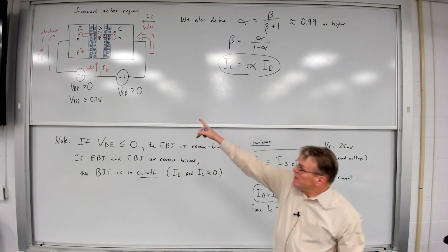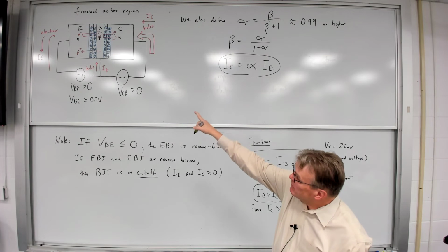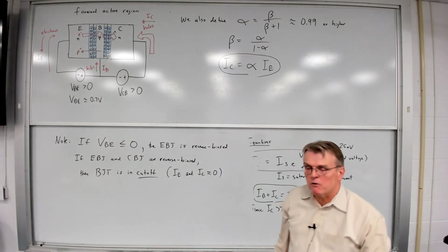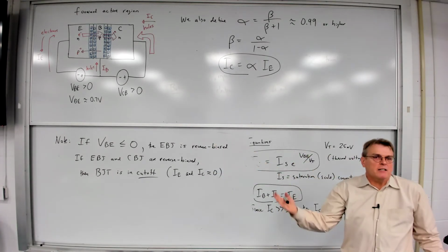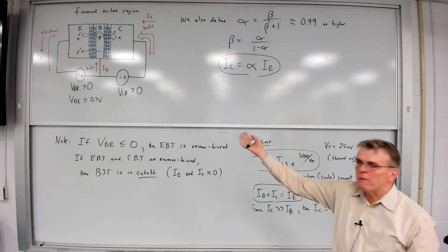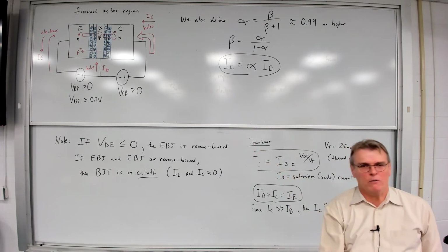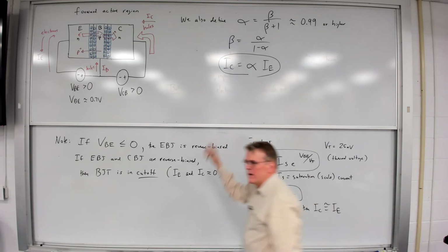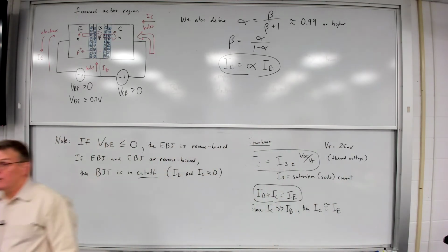Yes, a very, very tiny reverse bias current can flow across that reverse-biased emitter-base junction, but effectively the transistor's off. So just as when you have a reverse bias diode, you can have a tiny current flow. But in this case, they're both effectively off, effectively equal to 0.